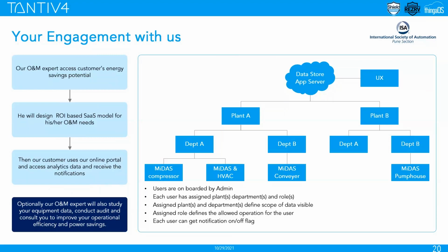In fact, there is an effort from the analytics group, what they call NILM, non-intrusive load management, by which we can measure at one point, which could be the incoming to the cubicle which controls the whole transfer line. We can find out the number of different electrical states, which actually means which motors are on when and how many motors are on at a given time, or is there a heater on, and so on and so forth. There's a significant effort that has gone into it by which we can find out different states.